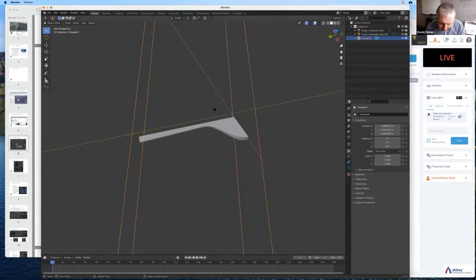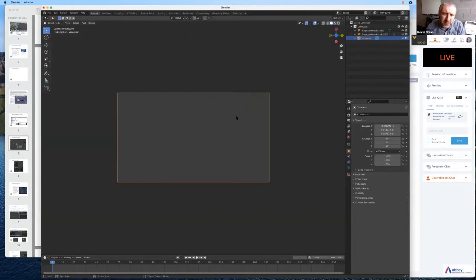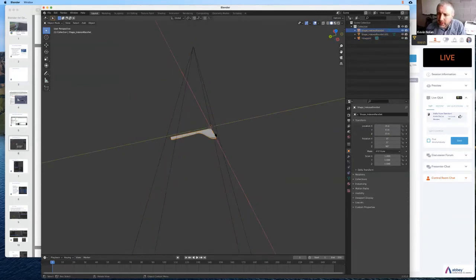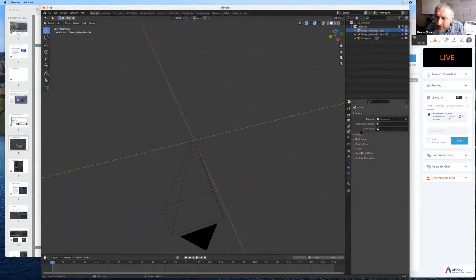Okay, so if I press the 0 key on my numpad, I see what the camera sees, and currently it disappears. Something's wrong. Now this simulation is brought in to scale. It's a very, very small geometry. Just for reference, by default each Blender unit here is 1 meter, and this is very, very small. So I go to my Scene tab, and you can see that there's a scale. So under units, you're using a unit scale of 1 meter. Now you can change that if you like, but there are other ways you can do it.